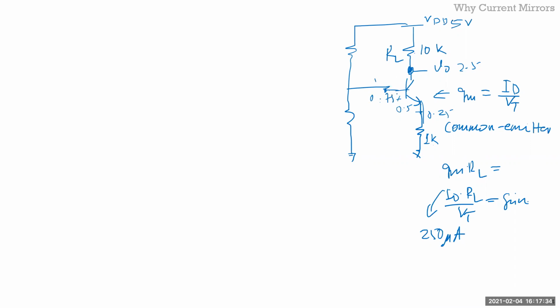So I can just put a resistor divider between VDD and the base voltage such that this is 0.75 volts. So let's say this was 5 volts, then you calculate R1, R2 and do it. And then in order to couple the AC signal in, you bypass this because you don't want to take this DC voltage and affect whatever it is driving. Like the cell phone example I was giving you, your cell phone has some DC bias into it. If you directly attach to it, you'll draw a huge current and you'll just collapse it. So you want to decouple it, but AC couple it for bigger signals.